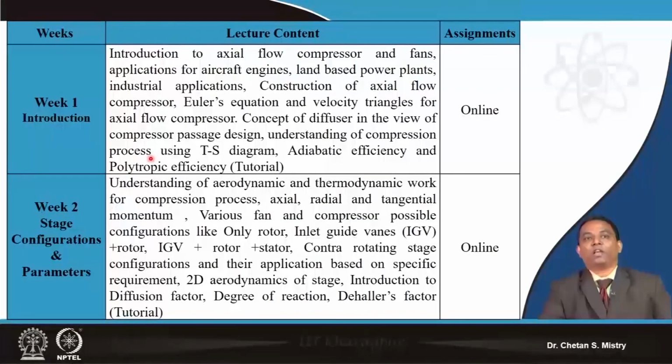You might have seen what we discussed for different engines, with combinations of inlet guide vanes, only rotor, inlet guide vane, rotor and stator configuration. We also have a future requirement, the counter rotating concept. All these things we will discuss in this session. We will also discuss a very important parameter that is required for our design.